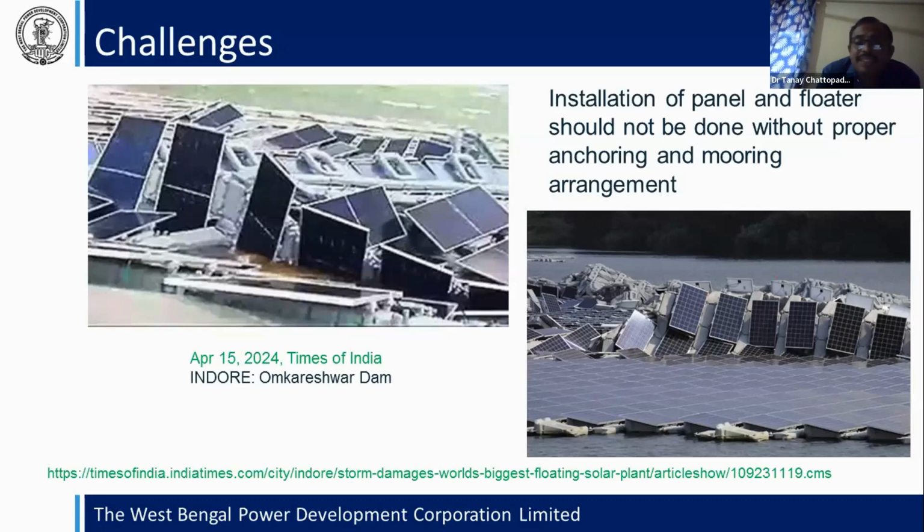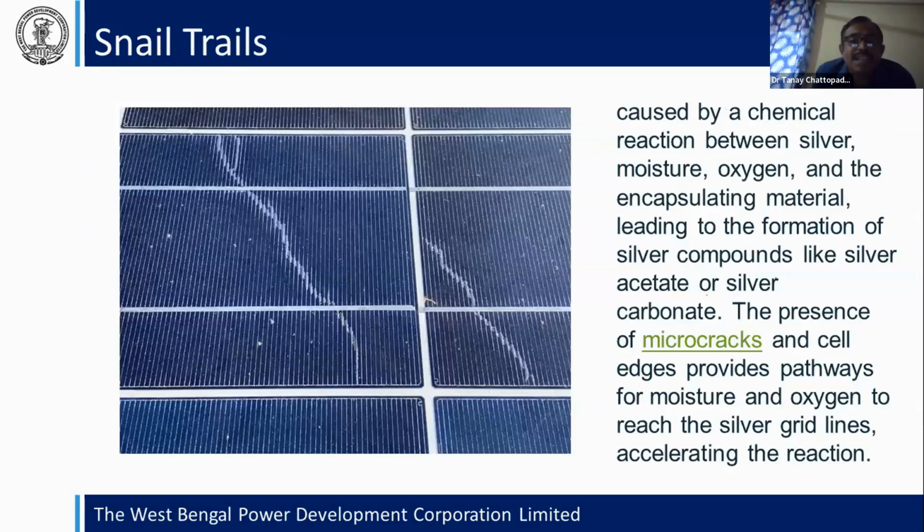Okay, and the main problem was that when water ingresses into the panel, micro cracks develop, and calcium carbonate and silver carbonate are deposited there and make this type of traces, and then this damages the panels.